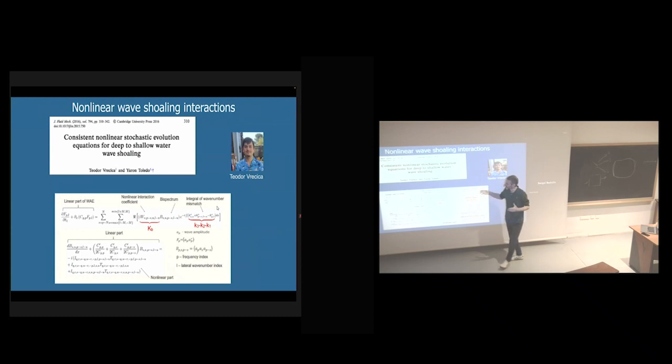So here you can see the stochastic model. That's the linear part of the wave action equation. So you can see the change of wave action, and just in quasi 2D, the change of the horizontal change. And on the right side, that's the wave action. That's what's written here. On the right side, because we multiplied with an amplitude in order to create on the left side a wave action and not just an amplitude evolution in the deterministic term.